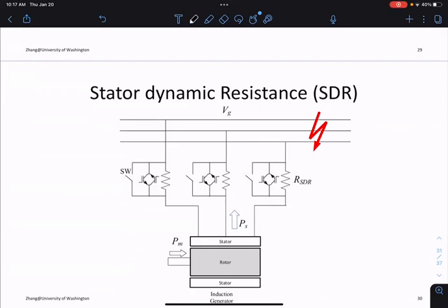We'll stop here in this class, because next class we'll compute some equations for these. You'll see that even for a very large resistance, you're probably not going to live very long. But you need pretty large resistances, and you can dissipate a large amount of power in a few seconds. You're limited by not melting the resistor. That's basically your limitation. So this is dynamic. The dynamic word comes from the fact that we're using the SCRs in parallel with these switches, so we have some control of how much power we want to dissipate.